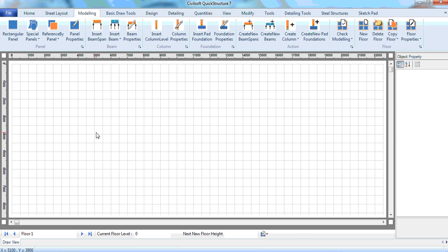Now next, I'll create my panels, and again I said this is my ground floor. It's my ground floor level. And as I said again, the ground floor is starting at 0 level. Now if your starting floor, let's say you have a basement, you can as well change this to minus. It can be minus 1350 or minus 6300, depending on whatever the starting floor level is. Then I will make my model.